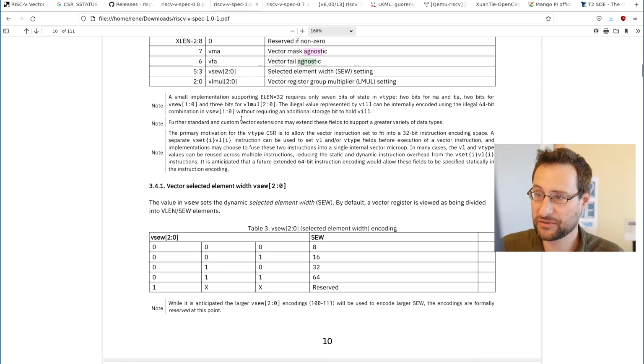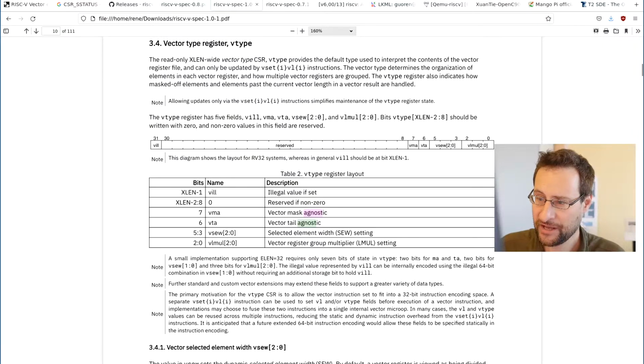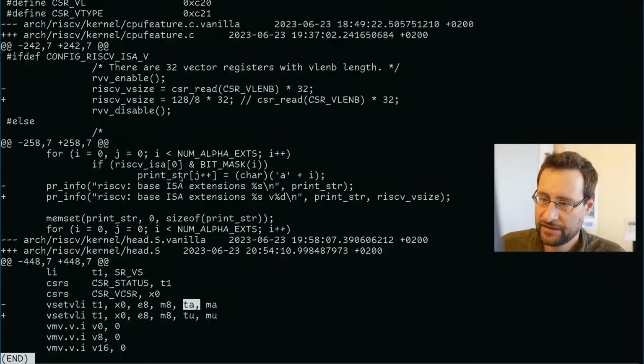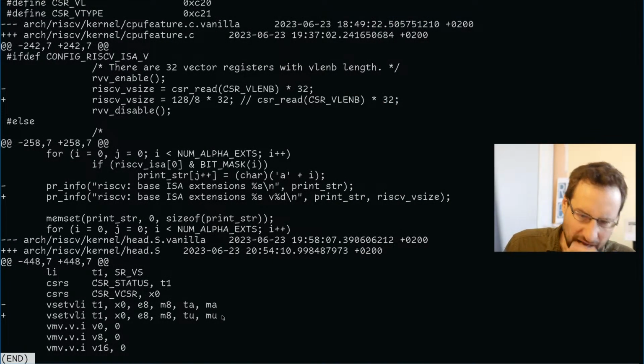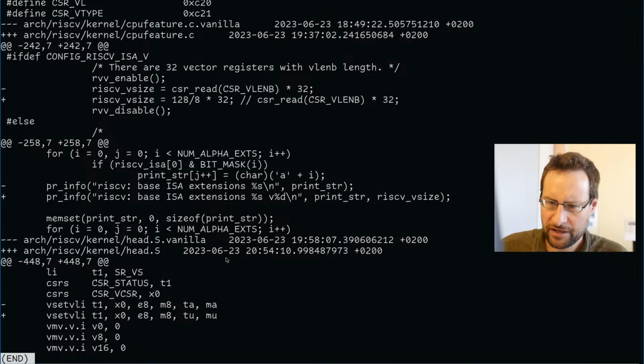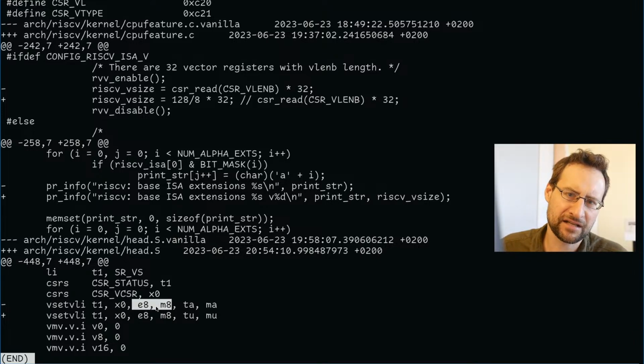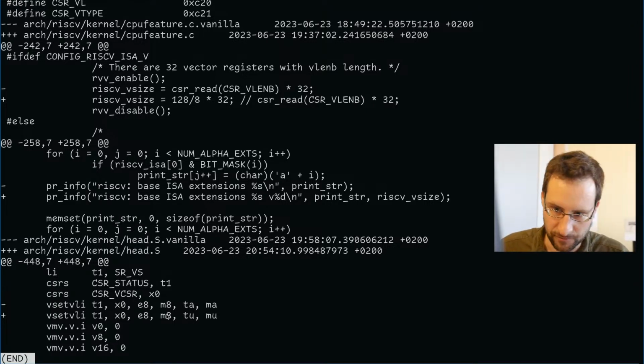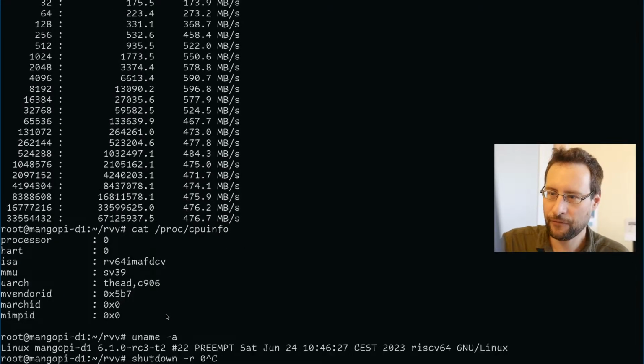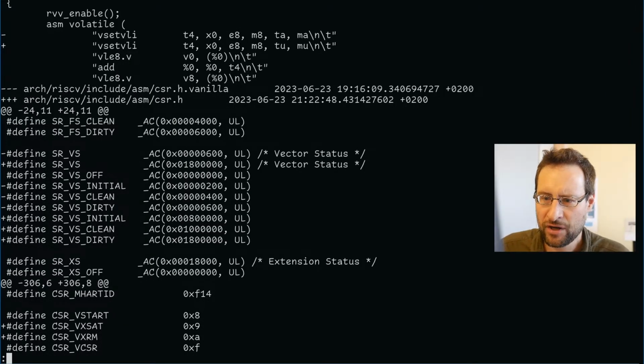Here, vector mask. So these 2 bits in the instruction in the V-type register layout that they added after 0.7.1. And so they need to be 0, right? I need to review if this is 100% correct for executing on 0.7.1. So basically, like this again, illegal instruction faults with this bit set. Otherwise, the other stuff is mostly, we are lucky that for element 8 and mask 8, I need to double check, but I believe the instruction coding is accidentally identical, hopefully at least. But hey, it works. So yeah, some stuff needs review.